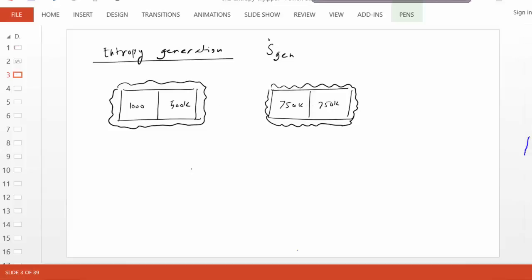We not only see it in temperature difference, we see that in many other difference-destroying natural phenomena. For instance, if we drop a drop of ink in clear water, you'll see the concentration difference being destroyed. If you have a voltage difference, a current will flow until the voltage difference gets destroyed. If you have a velocity difference, you'll find nature will try to destroy the velocity difference. It will invent a mechanism called friction, which will oppose the relative motion. And that's the mechanical friction we understand. Viscous friction is just another friction. When a fluid layer passes over another fluid layer, viscous friction will try to stop the motion.